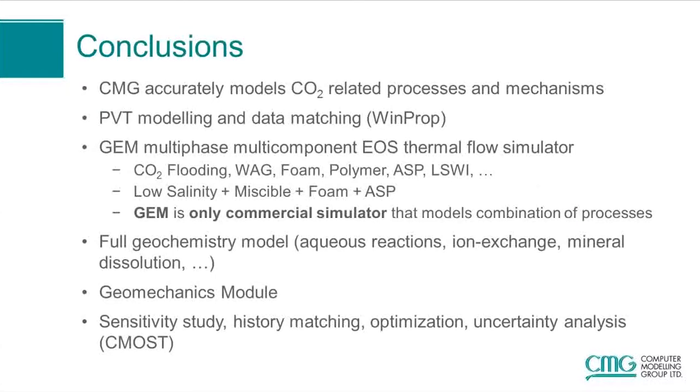Based on what I presented today, CMG can accurately model all the carbon dioxide related processes and all the mechanisms involved in these EOR techniques. So we have the WinProp package that can be used to create a PVT model based on matching all the lab data. WinProp can also model the asphaltene precipitation, and it can capture all the mechanisms involved in the precipitation and the redissolution of the asphaltene.